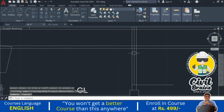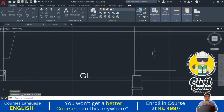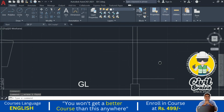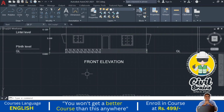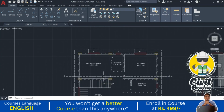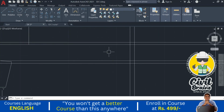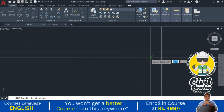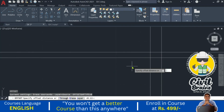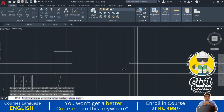So here only the wall is there. Now I just delete the center line. This is our plinth level, this is our lintel level. In the lintel level there is nothing, so I only show the lintel, there is no projection chajja. So here the slab, the projection is offset 0.45, that is the projection of the slab. I just trim the extra one.